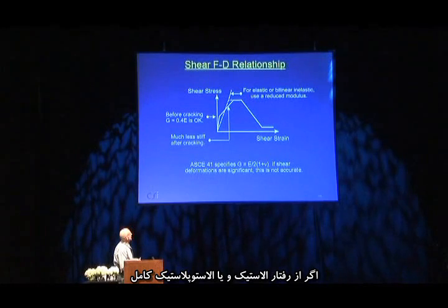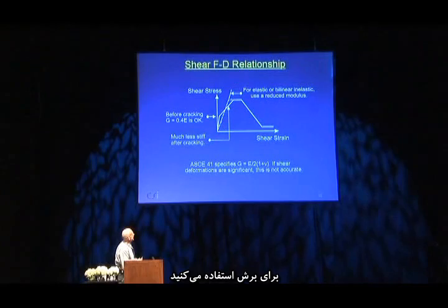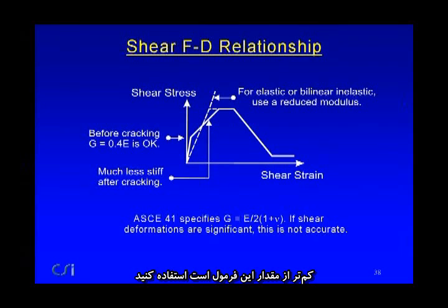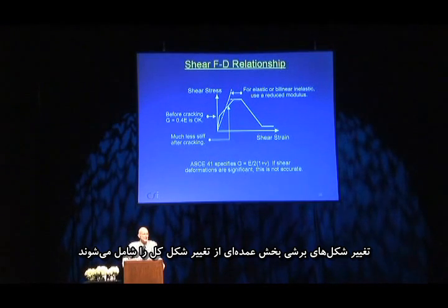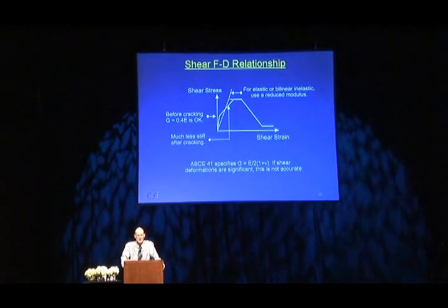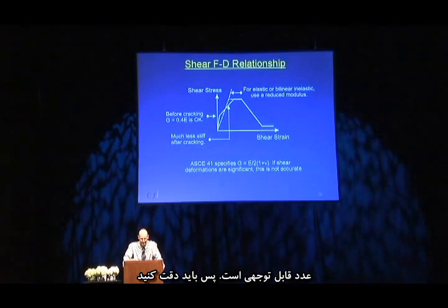If you were going to use either a linear behavior for shear or an elastic perfectly plastic behavior, you really should use an elastic modulus which is substantially smaller than is given by this formula. And it may be of the order of 1/10 as large. In many cases, the amount of shear deformation doesn't matter very much, and if you're off by a factor of 10, it may not have a huge difference. But as you get into walls, shearing deformations do tend to be more significant part of the total deformation, and if you're off by a factor of 10 on the shearing deformations, that could be a serious error. So you do have to be careful here.